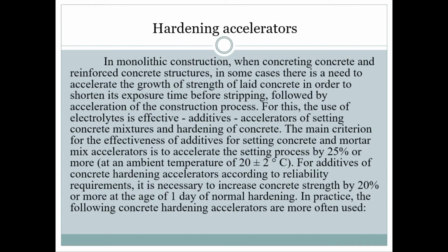Hardening accelerators in monolithic construction when concreting concrete and reinforced concrete structures. In some cases, there is a need to accelerate the growth of strength of laid concrete in order to shorten its exposure time before stripping, followed by acceleration of the construction process.